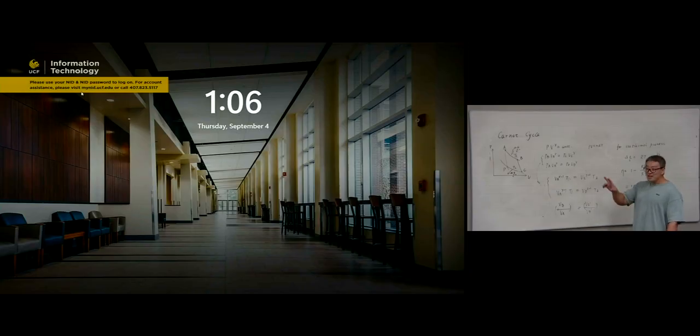No, they're not the same, but their ratio is a constant. See that one? VC divided by VD equals VB divided by VA. Then these two terms equal each other, and the long one I don't care about. This term is removed. And then the efficiency is just (T2 minus T1) divided by T2. In other words, we have the engine.